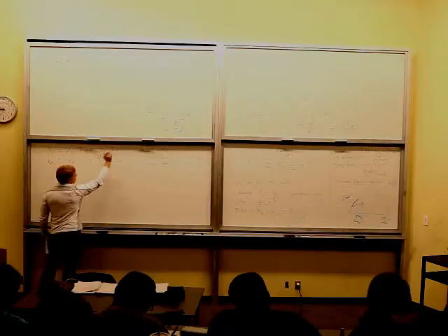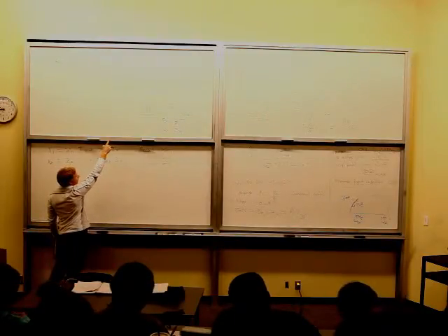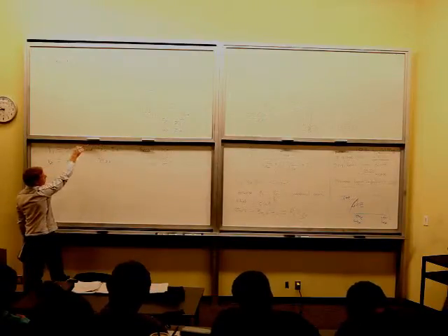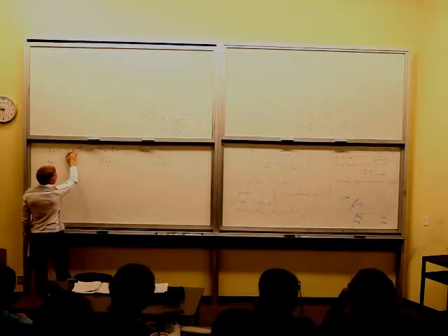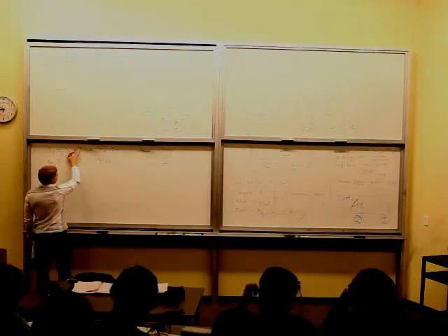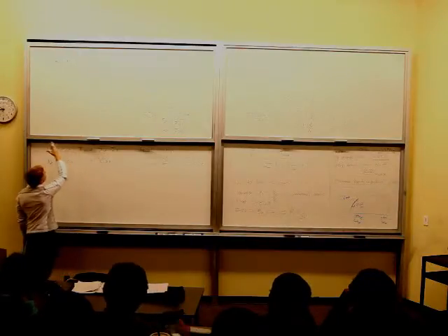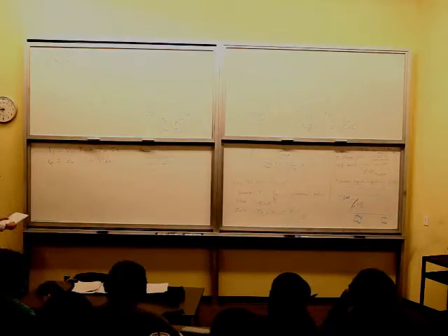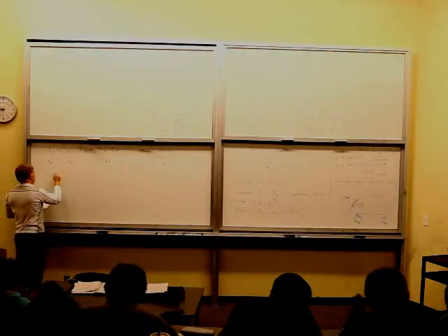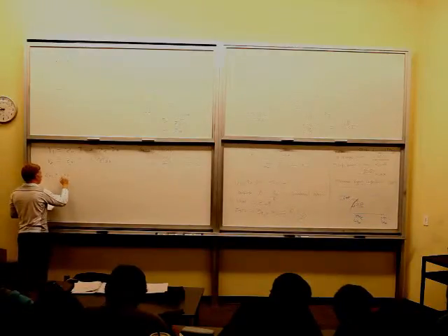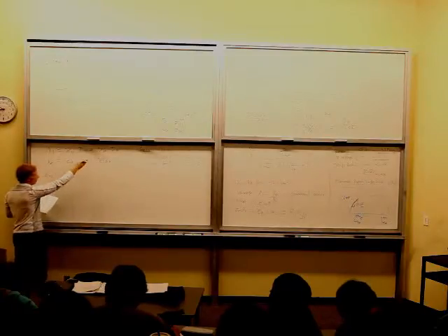And then what we do, so we shut off I2 by open circuiting that side. So we just leave it as drawn there, that right-hand side. And then when we want to figure out these parameters, we're going to open circuit the left-hand side, and we'll see how that works. So we're going to start with Z11. Z11 equals V1 over I1 when I shut off I2.